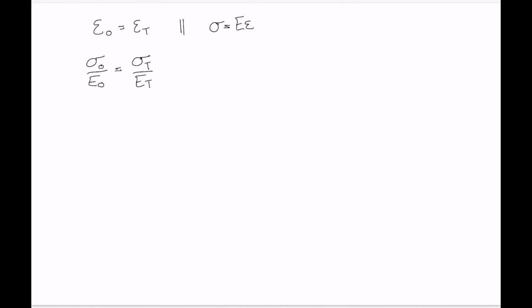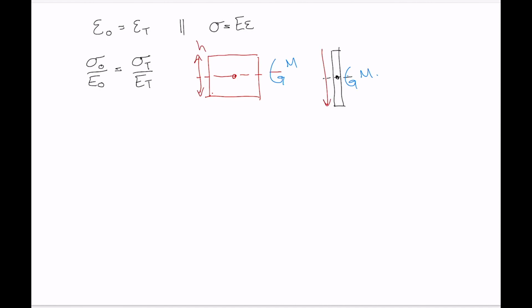So basically what we're looking for again is, we've got a piece of filler material like this. It's experiencing an internal moment M, and we want it to deform equivalently to a very thin piece of different material that experiences the same moment M. And importantly, we haven't changed the height of these, or at least if the moment was about the y-axis, we wouldn't have changed the base.